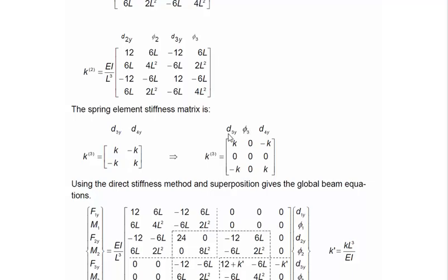So in this matrix, we add phi 3 correspondingly. We add a column and we add a row, but you see that these rows and columns have all zeros. So the objective of adding this one row and one column is to make the degrees of freedom consistent. Otherwise, there are no numbers here, so they don't have any effect.